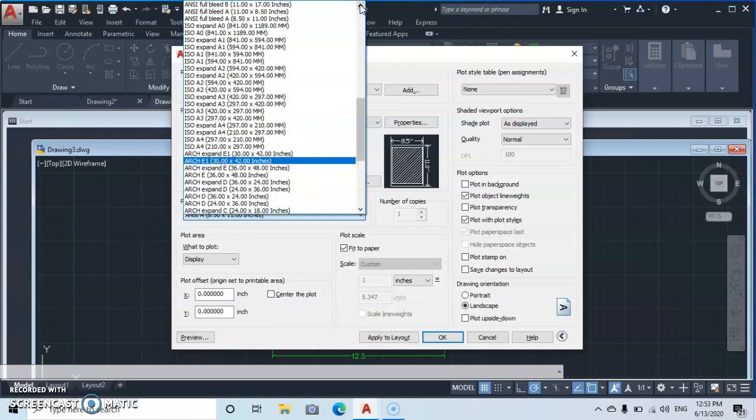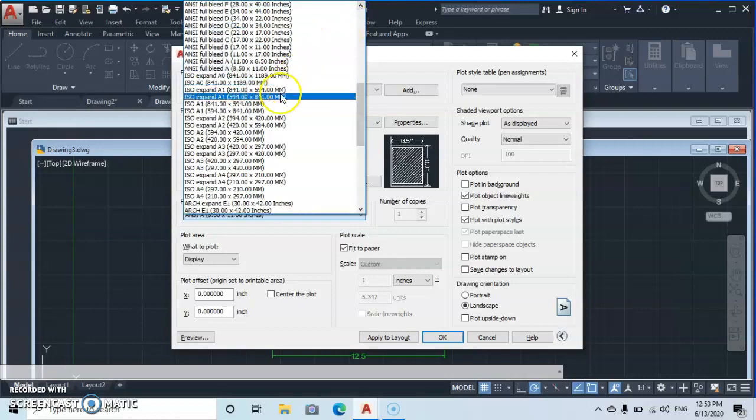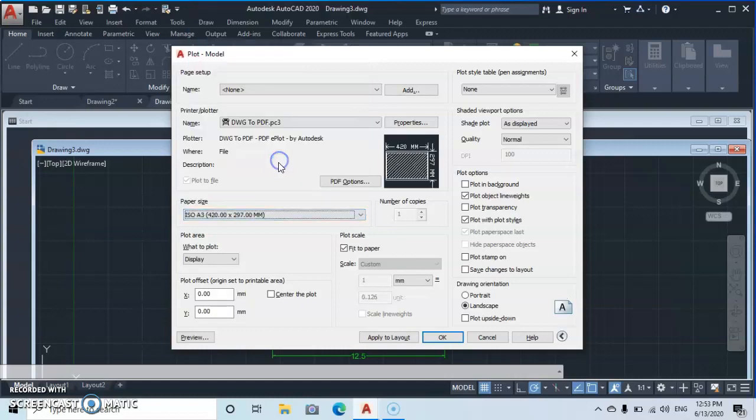In this case, I would like us to save our drawing in A3, ISO A3 paper. Okay, let's do it horizontally. So I'm going to select A3, 420 by 297 in size. Okay, that's millimeters. And then we click here. Then we continue. Let's move over here to check.